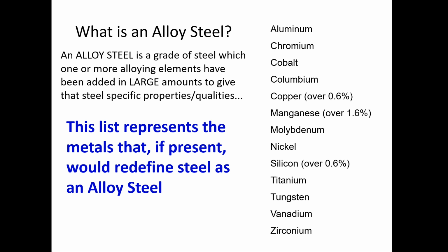The nice part about alloy steel is we have enormous control over what we can do with them when it comes to heat and temperature. We can create gears, we can do all kinds of things and harden the surface, but keep the material in the middle soft and annealed so it's not brittle, but the outside wears hard. We can do all kinds of things. The downside of these materials is they're all reactive to heat. It's almost like a double-edged sword, because being reactive to heat, we have to make sure that we don't transform them when we weld, so we don't make the machinist very angry at us when we're over there trying to machine it and we have to take it to a grinder just because everything's so tough.